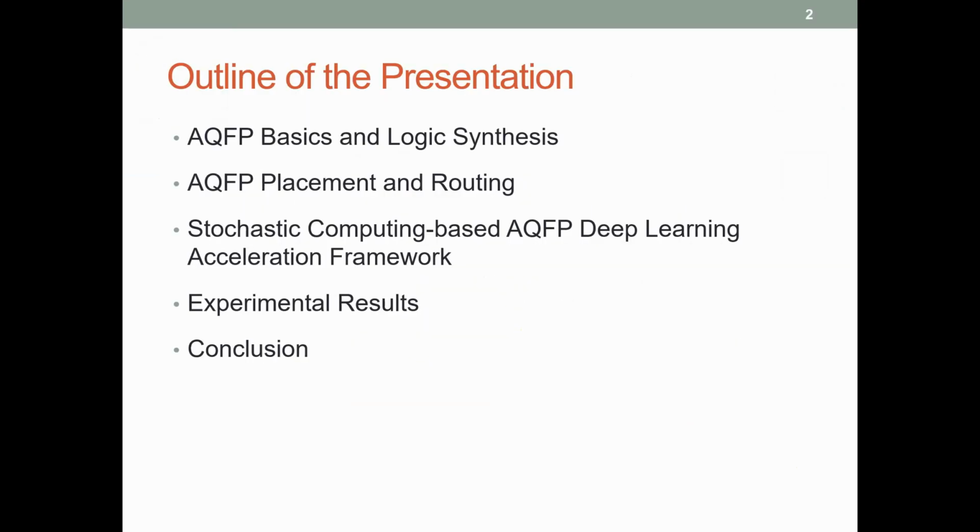So the outline of this presentation is shown here. First, we're going to discuss the AQFP basics and also the logic synthesis. And then we're going to discuss the AQFP physical design flow, including the placement and routing. And after that will be the stochastic computing-based AQFP deep learning acceleration framework, which is our ISCA paper last year. And then we'll discuss experimental results, including the actual tapeouts, and conclusion. The actual tapeouts are done by Yokohama National University.